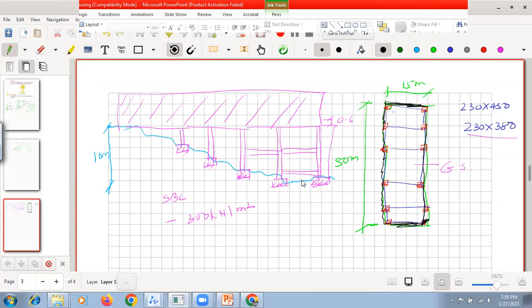But here we decided not to go for this because the cost of the project will be too much. A 10-meter high retaining wall will be too heavy and very costly. That's why we prefer to go for the columns with the tie, and one additional slab had to be considered. The suspended slab had to be considered at this particular level. And we went further.